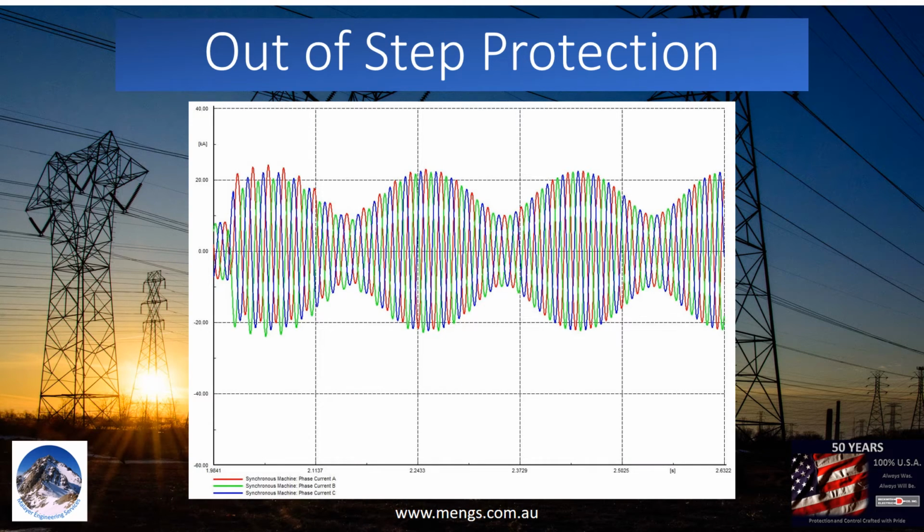During pole slip, machines experience very high current, usually higher than the 3-phase short-circuit current, which is dangerous for machines and the system. Generally, an out-of-step condition has to be detected fast, and the out-of-step machine has to be isolated from the system. In some conditions, machines might regain synchronism after a few cycles of slipping. In this case, a pole slip counter counts how many times the poles crossed each other.